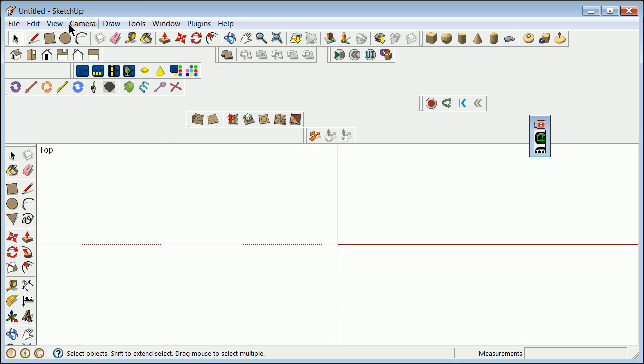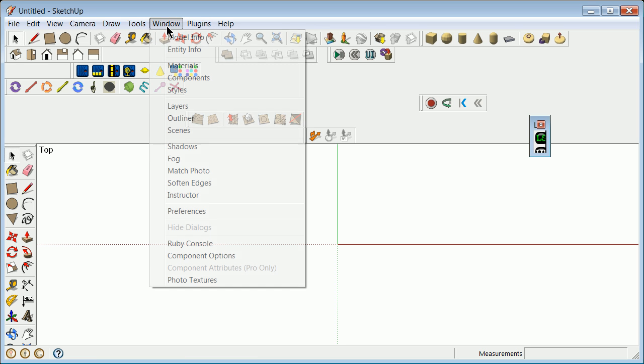Anytime you start in any program, you get some things, typically like templates, thrown at you. It's still a good idea to learn to check the units, the coordinate system, and the assumptions on anything you do whenever you're doing it. Knowing whether you're in inch units or feet units or meter units, whether you are in a right-hand coordinate system like most things or a left-hand coordinate system when you're doing civil work. And so on this program, the units are going to be set down through some of these pull-downs here. So let me start with that.